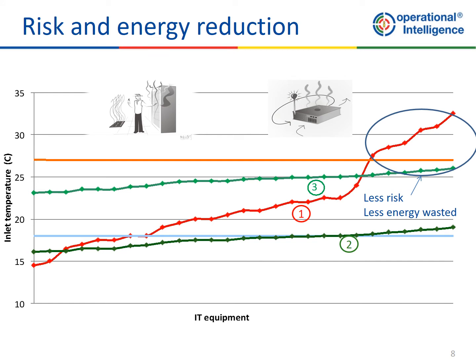So if you were to do a survey inside the data hall of all the servers, in this case there's, I can't remember, 20 odd servers here. That's one, that's another, that's another, that's another. And all we've done here is just put them into ascending order of inlet temperatures to the servers. So we've got a rack here at 14, 15, 16, that's 20. And you can see here you've got even air temperatures going in at over 33 degrees there.